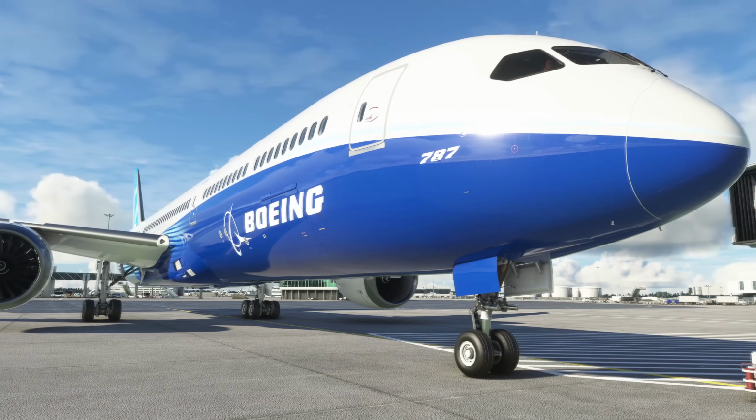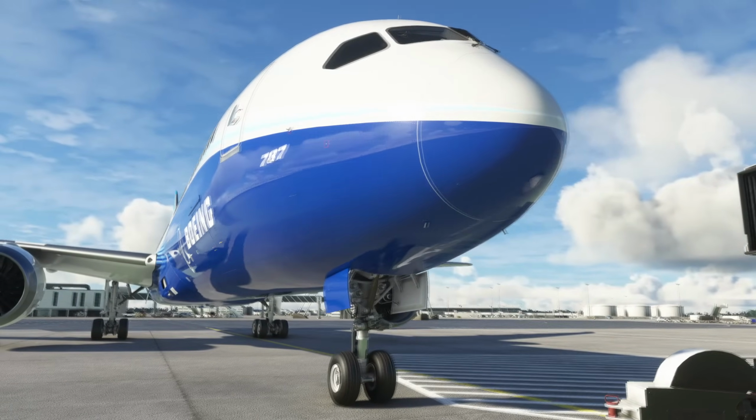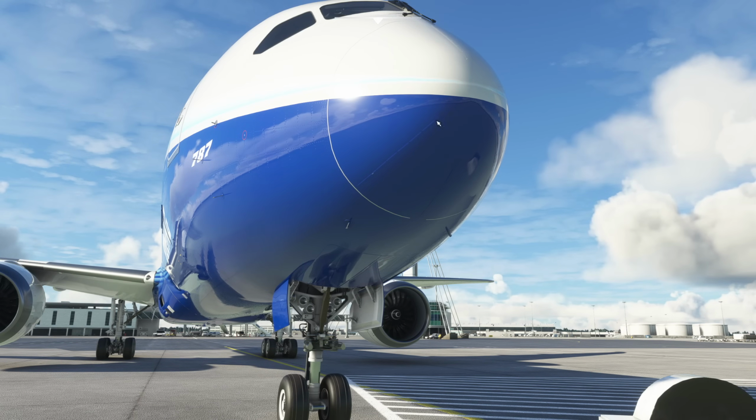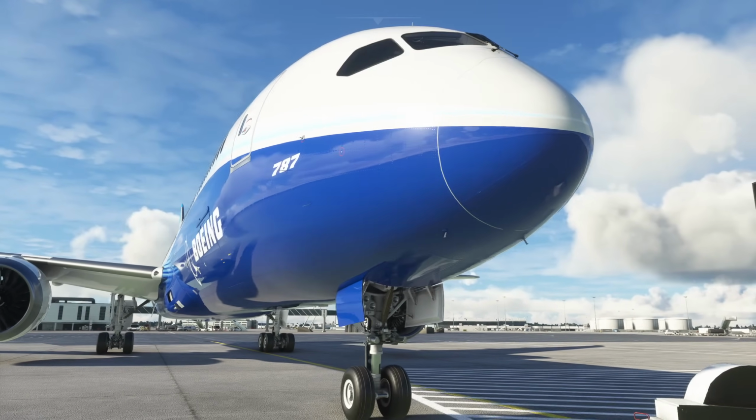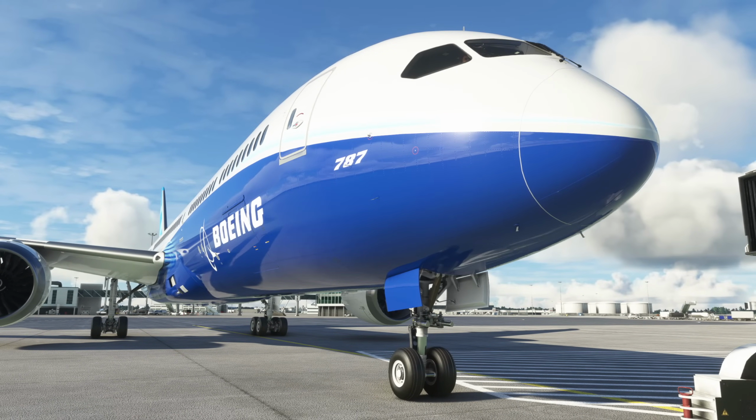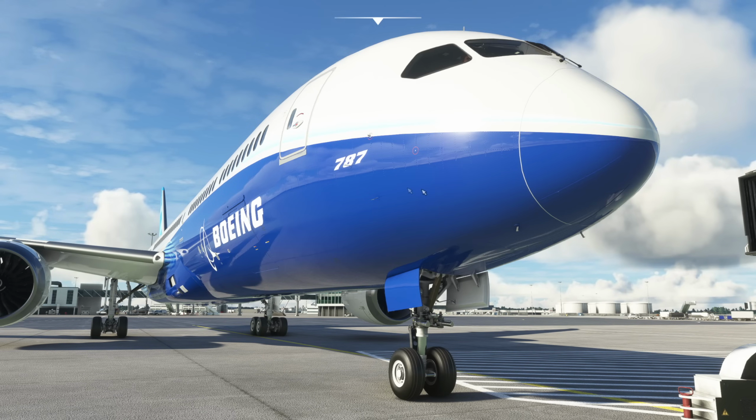One strange effect is, and you can actually see on the nose gear, we have these lightning strips, these static lines to take lightning away, to take the electricity away and flow it in certain channels around the aeroplane. So if lightning does strike the 787, unlike a metal aircraft where you'll typically get an entrance point and an exit point, so there'll be maybe 2 small holes, you end up with a series of tiny holes in the fuselage, which don't affect the aircraft at all, or the pressurization, but they do just form in a long line. It's quite strange, and not something I'd expected.